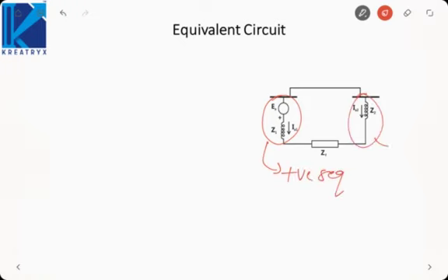This one is your negative sequence. Here we haven't connected the zero sequence because zero sequence current is 0. Hence the zero sequence circuit is open circuited. And the impedance connected between the two networks is ZF. Now if you see here,